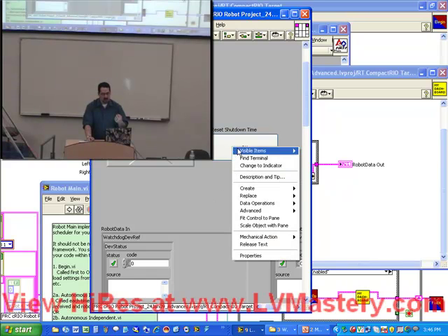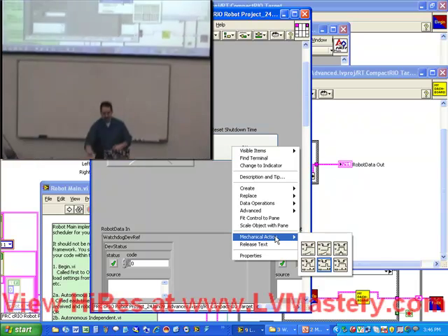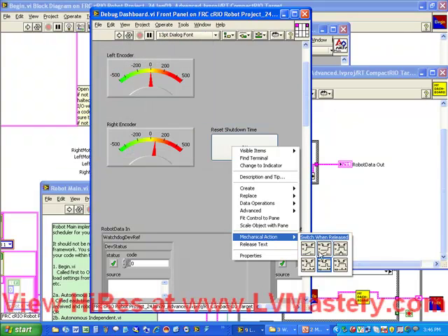But if you didn't know that, you can always check by right-clicking, choosing mechanical action, and here you've got two sets of choices, the switch choices and the latch choices. You can experiment a little bit, but just be sure you choose a latch one. I advise latch when released. Latch when released, basically, it's like any Windows button. If you accidentally push the close button in Microsoft Word, you say, oh, I don't want to close, and you move your mouse before you let go of the click, it doesn't actually do it. That's latch when released. Okay?